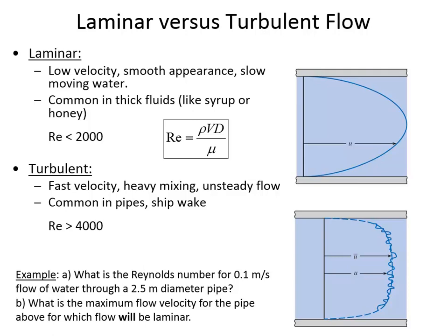All right, it's the point that you're furthest away from the pipe friction. Remember when we were talking about a plate being pulled through liquid? I think we had a tank of glycerin, and we were pulling that plate through a liquid, and there was a velocity distribution where the liquid that's right in contact with that plate is moving along with the plate. It's touching the plate and it's getting dragged along with it.